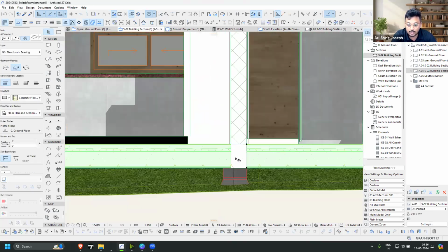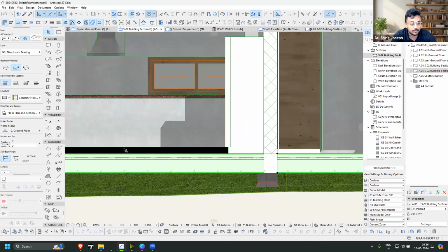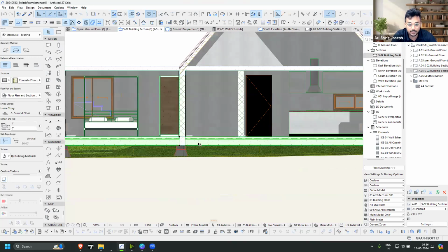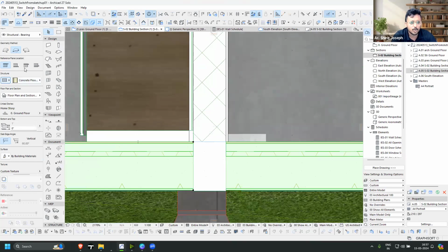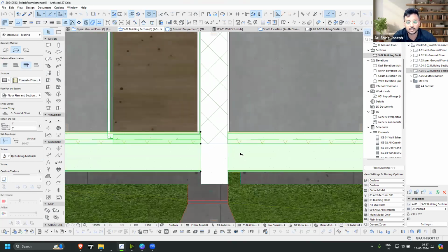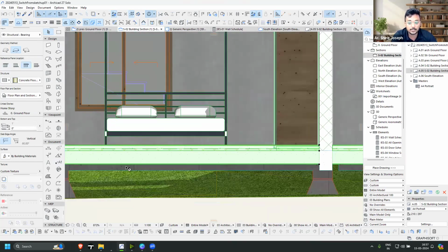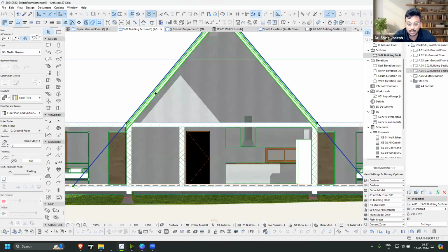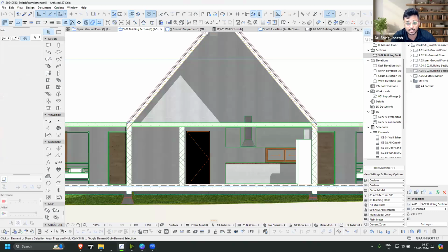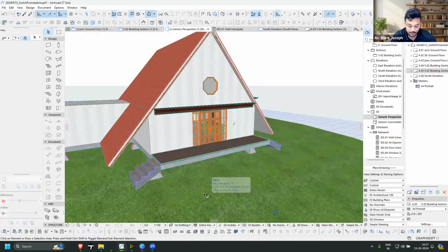And you can see the beam automatically is cutting this slab here due to its property. And if I change where the reference level is taken, and if you remember, we did the reference level as the finish, that's why you can see it here. But if I change the reference level probably to the top of the core, the finish layer is going to be moved up, and it will also automatically get trimmed. So this parametric aspect is happening by default, and you can also do a lot of edits on this. You can cut the slab using some of the tools that we have already explored in the previous stage. So this particular composite will help us a lot in terms of adding these particular properties.